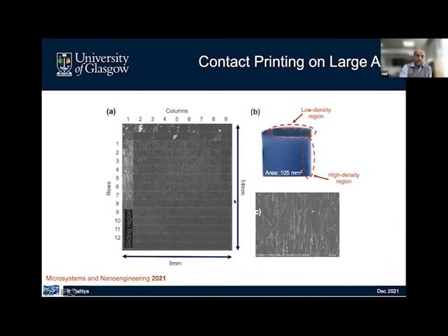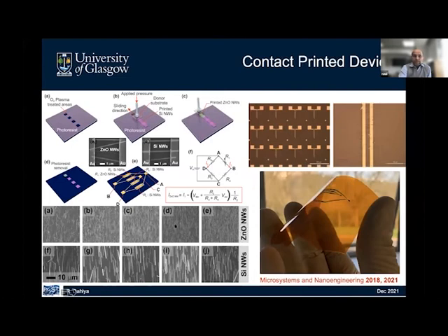In this case, the electronic layer based on nanowires is 14 millimeters by 9 millimeters, and we process this further to get various devices. One example is shown here as a photodetector. The zinc oxide nanowires and silicon nanowires were transferred on polyamide substrates. Zinc oxide nanowire was used here as a photodetector, and the rest of the wires were used as a resistor. That way we are able to develop various sensors, using these nanowires as well as transistors.